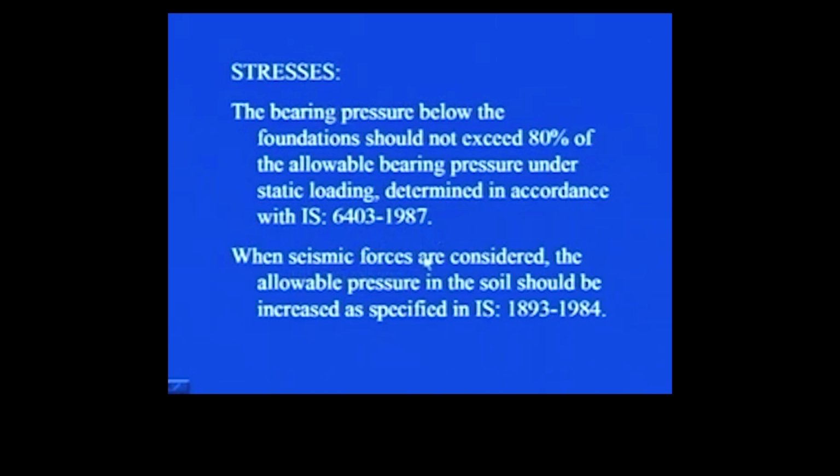When seismic forces are considered, the allowable pressure in the soil should be increased as specified in IS 1893-1984.